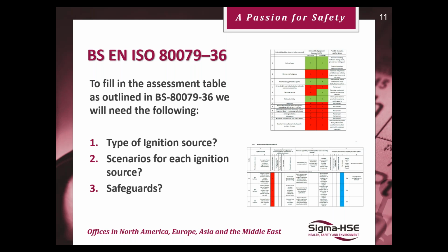As I mentioned, there are 13 types of ignition sources that are most common in industry. In NIRA, the non-electrical equipment ignition risk assessment, we don't take account of unsuitable electricals, because electrical installations have their own standards and compliance. So we can usually only look at three types of ignition sources: hot surfaces, mechanical sparking, and static electricity or electrostatic discharges.